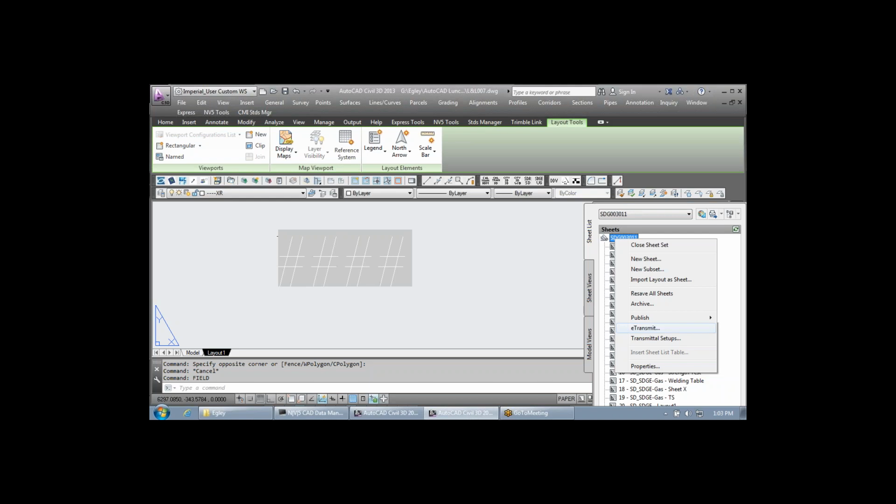But keep in mind that we can add those fields to our standard title blocks, or the same block that we insert all of our attributes. We can incorporate fields into those, and instead of using those block attributes, use these fields. So do you put the attributes in the XREF or into an insert? You can XREF or insert.